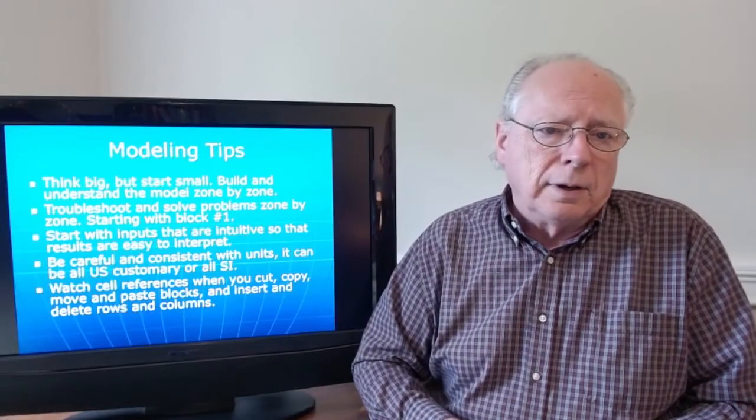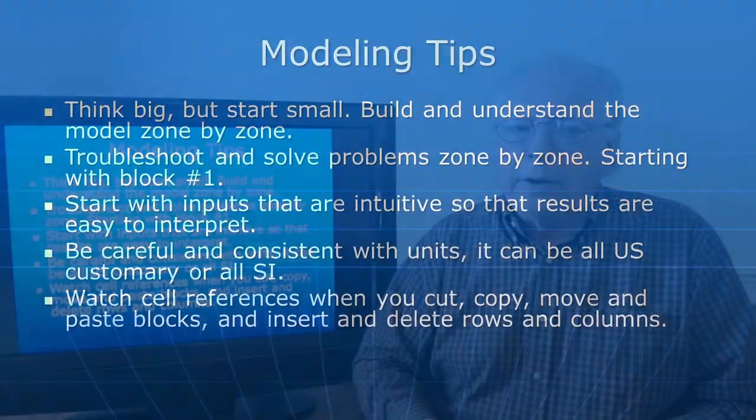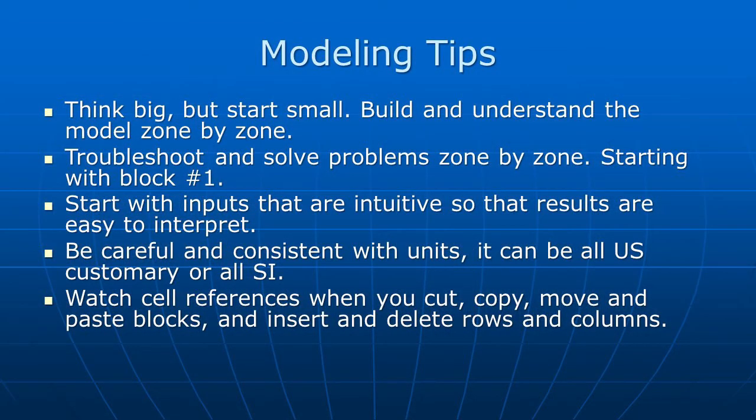Some modeling tips here: think big, but start small. So I had the whole model in mind when I started, but I go through and build it up and understand it zone by zone. I've seen people build these monster models, and they start off and all the numbers are crazy and they don't know where to start. So I usually start as we did with the first model, with the first zone, get it working, understand what it's doing, and then move on to the second zone, get it working, understand what it's doing. Troubleshoot and solve problems zone by zone.